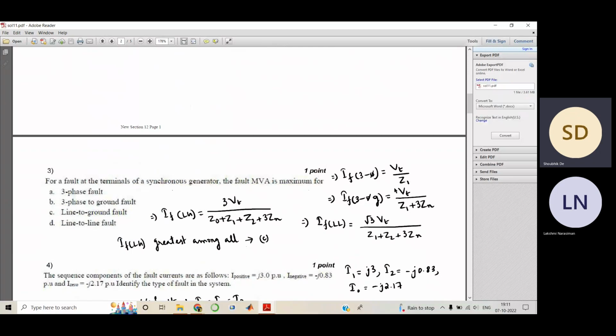In that case, because you have a high Z0 value for a long length of power system, considering transmission line, transformers, and synchronous generators, your three phase fault would be the most severe. Because they have asked how severe the fault current would be at the terminals of the synchronous generator, for this your line to ground fault would be the most severe. I hope my explanation was clear.